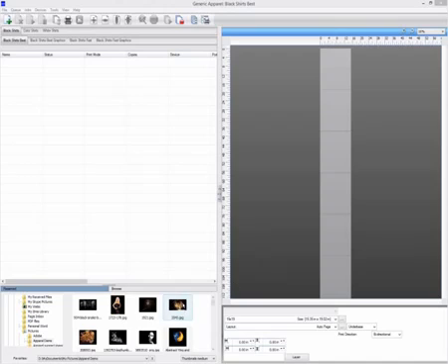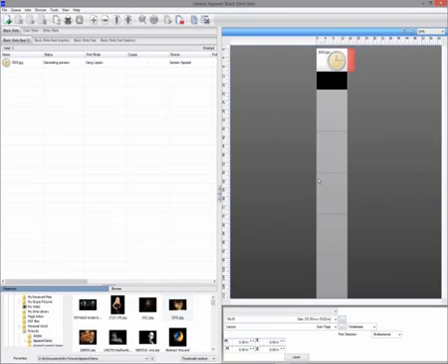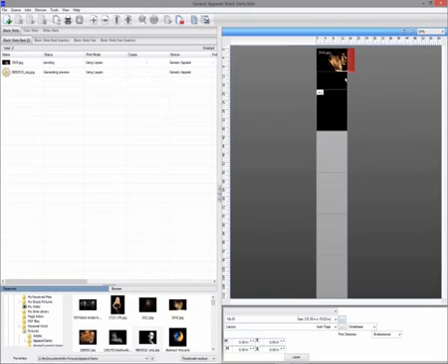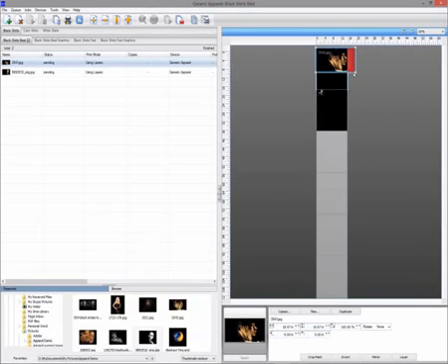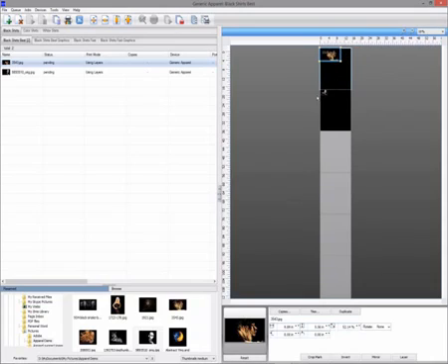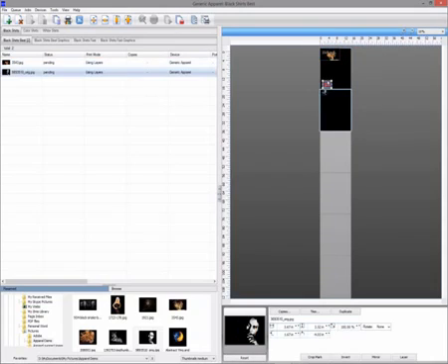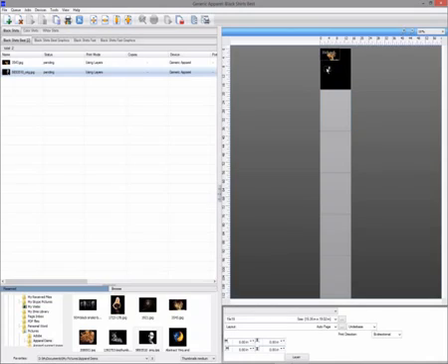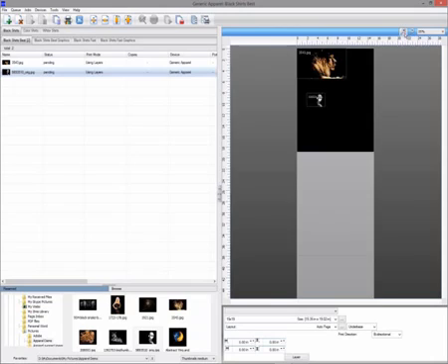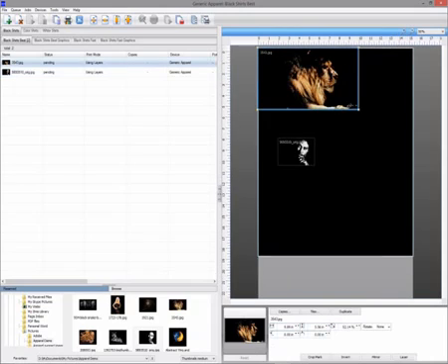You can now lay out multiple jobs on a single sheet. Each job will by default be imported onto a new sheet. To move a graphic between sheets, hold down the Control key when dragging the graphic in the preview mode. In fixed sheet mode, you have a lot more layout tools, such as cropping and tiling.